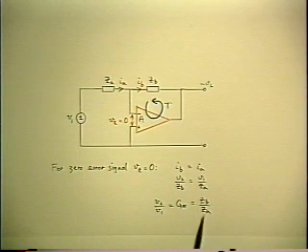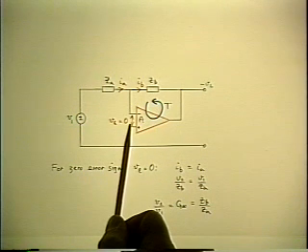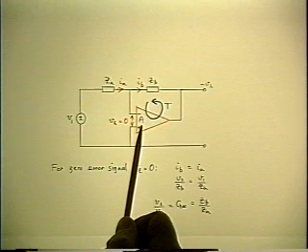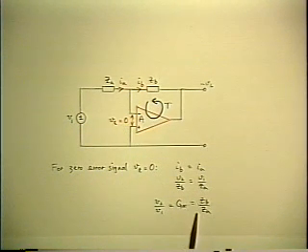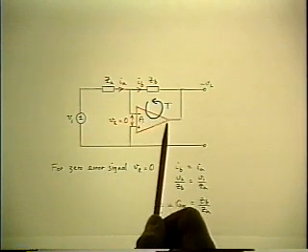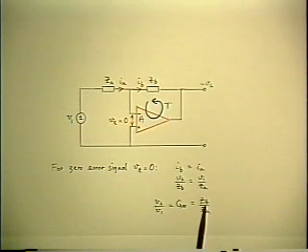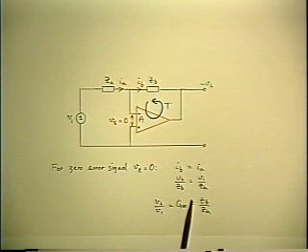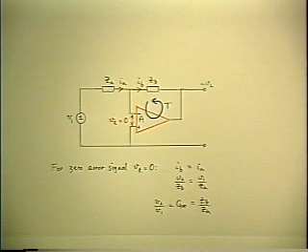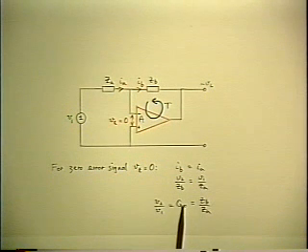But once again, what you really calculated is G infinity, because it embodies this assumption of infinitely large gain of the forward path. So it again neglects the fact that there is a D factor, which comes in when the amplifier gain drops off at higher frequencies. So the same result. What you've calculated is really G infinity, and you oughtn't to forget the other part of it, which is that the T and the D ultimately will go away, and the actual closed loop gain will cease to be equal to this ideal value.